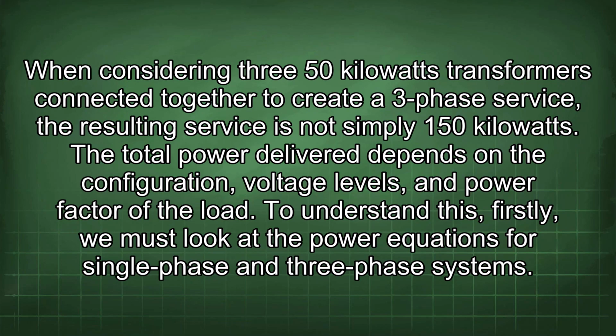When considering three 50 kilowatt transformers connected together to create a three-phase service, the resulting service is not simply 150 kilowatts. The total power delivered depends on the configuration, voltage levels, and power factor of the load. To understand this, firstly, we must look at the power equations for single-phase and three-phase systems.